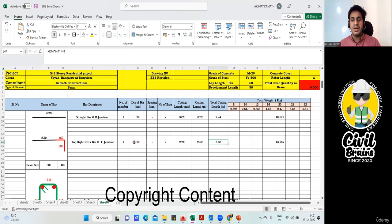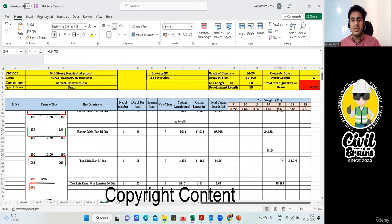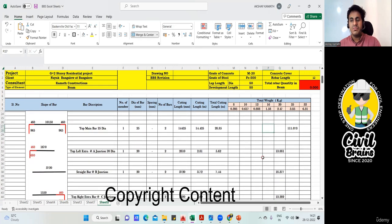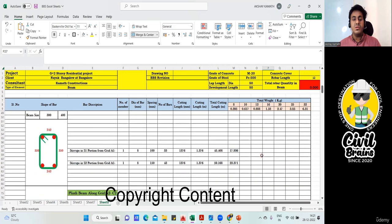Now, since it's a 20 diameter bar, I need to put this in the 20 diameter column. So again, 5.38 multiplied by 2.47 will give me 13.289 kg of steel required. Got it? Great. That's it. Other than that, the rest I've explained, how it has to be done. This is not required, we'll delete this. Rest all is clear. That's it. Finish. So in this way, you have to find the cutting length of the bar.